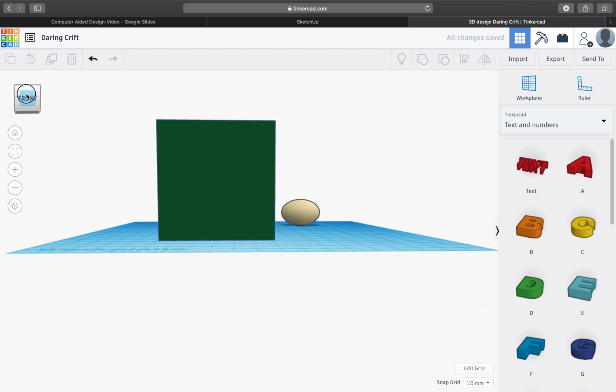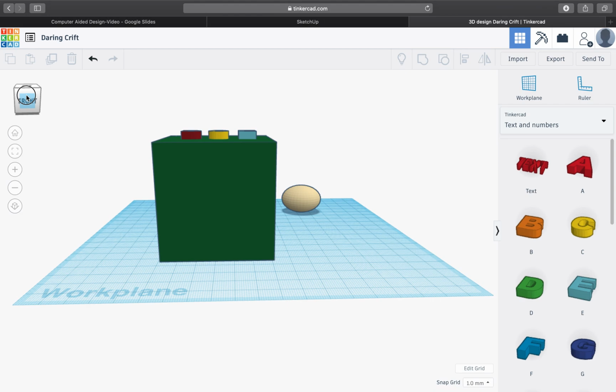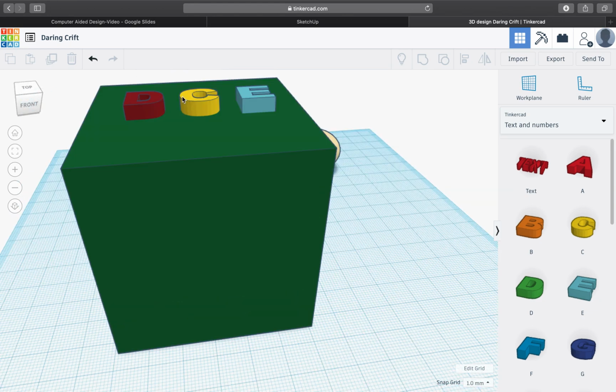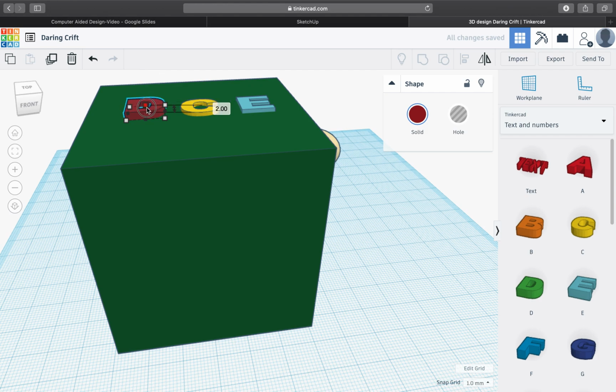We can also resize those letters. All right, remember we can zoom in there. We can resize them. Take each letter. If we want them to be flatter, that's at 4 inches off the top of the face. We can go down to 1 to give it a slight raised appearance. Now remember, when we're having things raised, it's very, very important to use the work plane for this, because this system is designed for 3D printing.